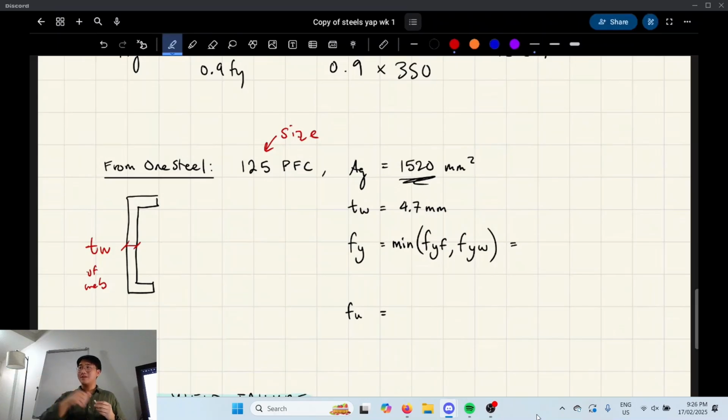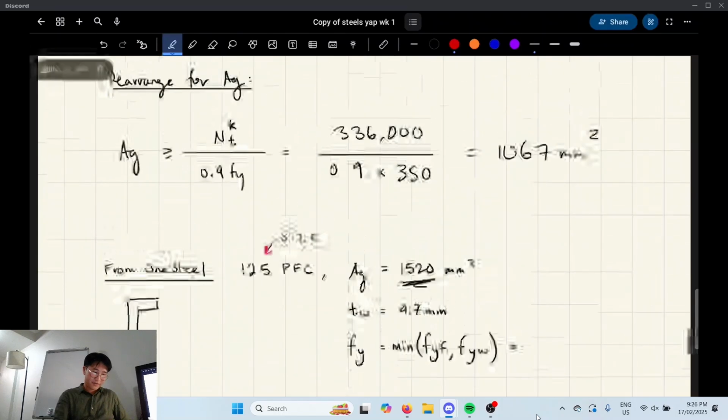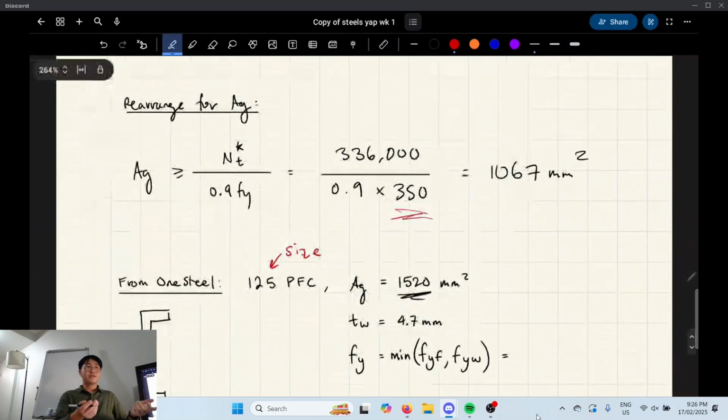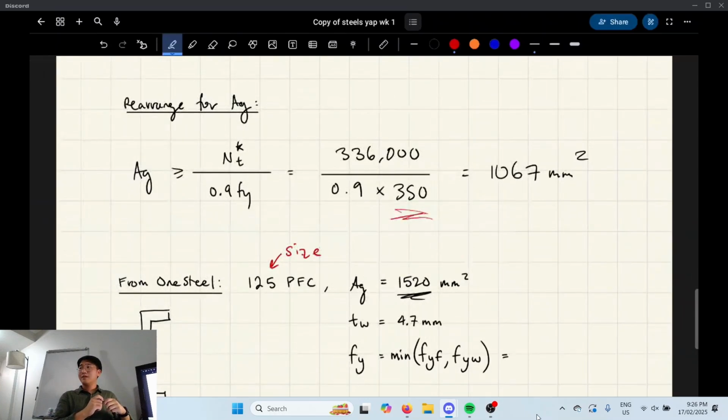So Josh might have the table up. What changes? It's called grade 350 steel, right? And for the initial guess I used 350 MPa, but it's not always 350 MPa, is it? Why? Because of the shape, kind of. Because there's stuff for flats and sections, there's things for hexagons. Flats is just any rectangle basically. So these are both rectangles, the web and the flange. But what do you reckon? Why would they have different yield strengths?